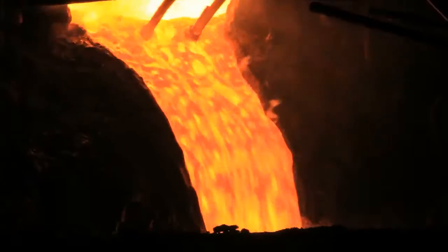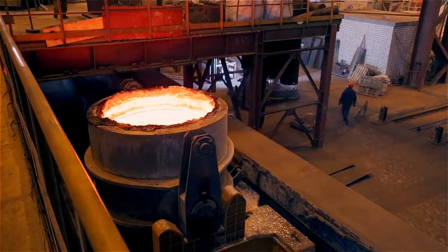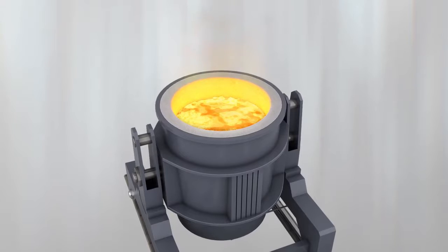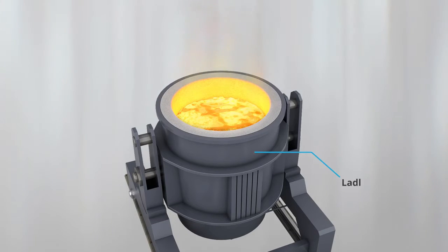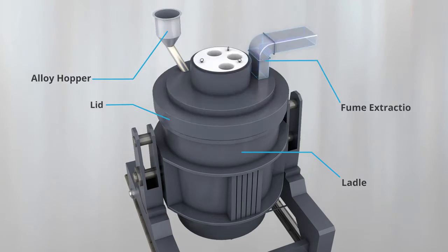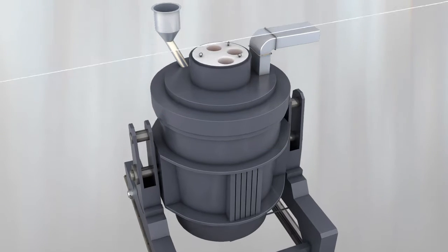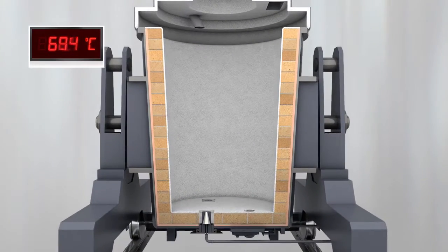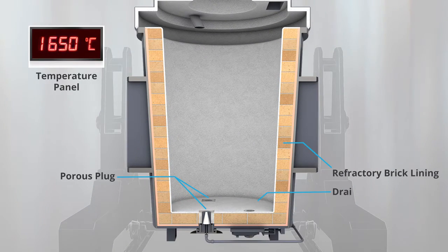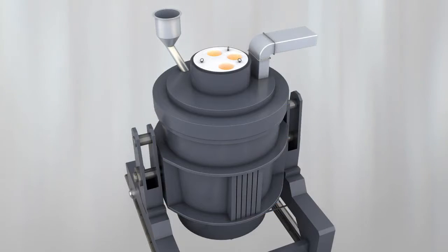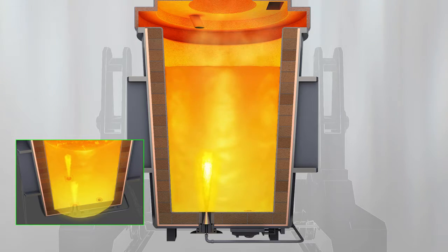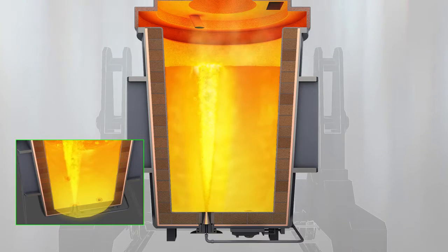Following primary steelmaking, molten steel is usually tapped into ladles, which are in effect very sophisticated and robust containers capable of holding up to 300 tons of liquid steel. It is in these ladles that various key alloying additions are made, and the overall process is referred to as secondary steelmaking. The ladles must therefore be capable of containing the liquid steel at a temperature between 1600 and 1650 degrees centigrade during several lengthy procedures, which may include deoxidation, degassing, stirring, decarburization, desulfurization, and the addition of ferroalloys.